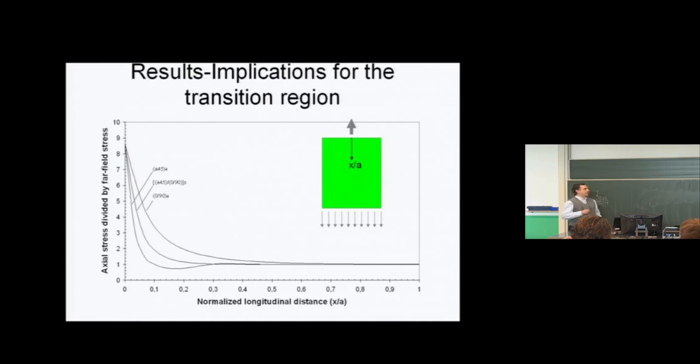And so I'm doing only 3 different laminates just to see the different trends. This doesn't mean you would only use those, and you would need either a more rigorous way of picking your laminates or definitely some other perspective that says, okay, if for some reason we need to use this type of laminate, make sure you include it in the ones you compare. What I've done here is I've included the plus or minus 45, which is the one we have been checking so far to compare with finite elements, which is a very soft laminate because the fibers are in the plus or minus 45 direction, so in plane in the 0 and the 90 direction it has relatively low stiffness.